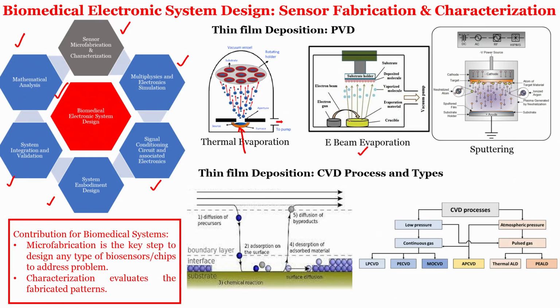The third one that we have seen under the vacuum deposition is this sputtering. Sputtering is a mechanical way of dislodging the atoms from the material, and those would be deposited onto the surface, right. That is using the argon gas, and the substrate is at anode and the target is at cathode, and when we apply a voltage there is DC sputtering, or if you apply RF then it is RF sputtering.